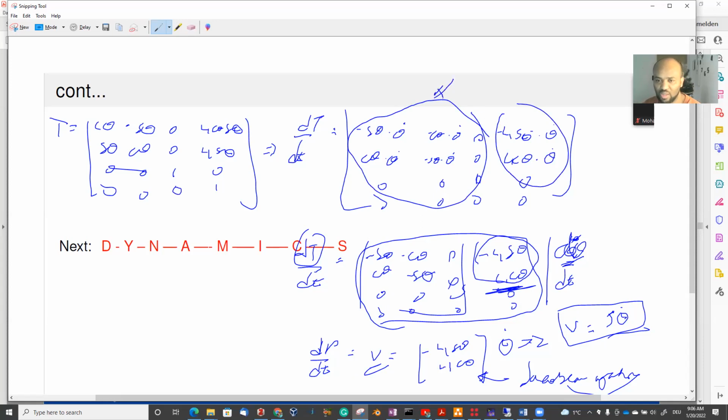This is the orientation of the rotational velocity; actually, we don't care about that. But here there is the linear velocity v, which is connected with theta dot, the joint variable velocity, the rotation theta in time, and it is linked with the Jacobian. So the linear and rotational velocities are related by a Jacobian matrix.